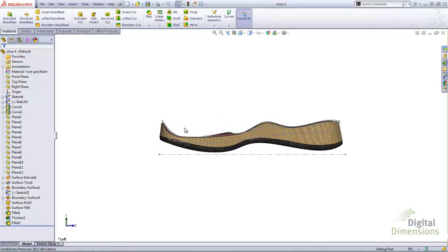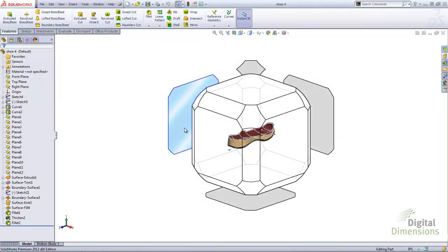Outside of using the orientation menu, you can also access the View Selector by pressing and holding the Control button and depressing the spacebar. This will show only the view cube without showing the orientation dialog. Again, selecting any face on the cube will orient the view normal to it.